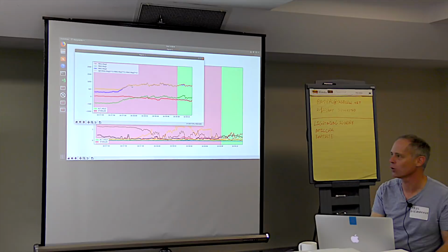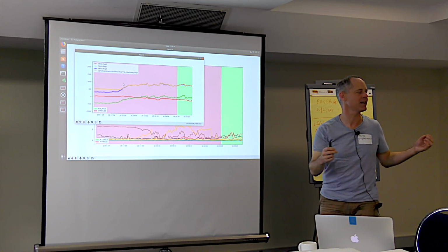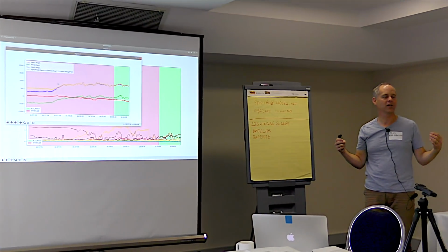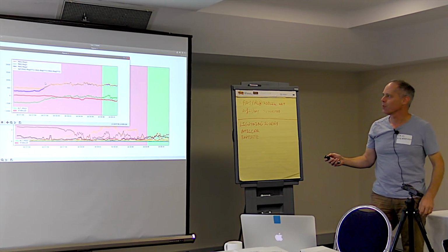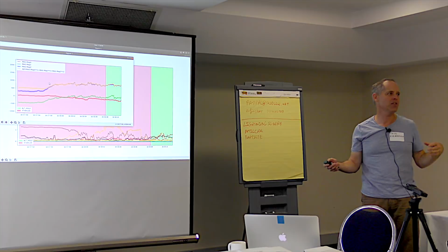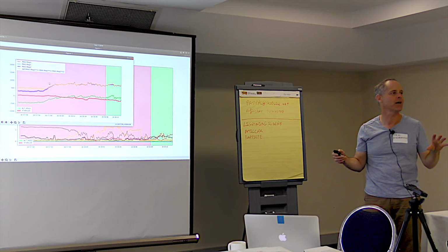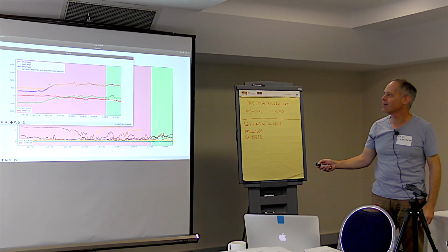And I'll show you the throttle. Now, we talked before about the importance of having a consistent magnetic field strength. If the magnetic field strength isn't constant, that's an indication of a problem with either calibration or magnetic interference. We talked about how anything more than about a 15% variation, I'd be pretty uncomfortable calling a reliable setup. Here, we have a variation.